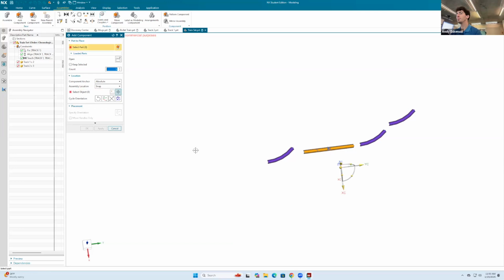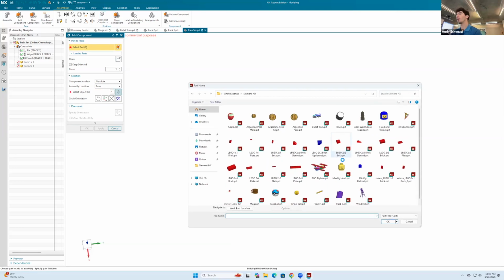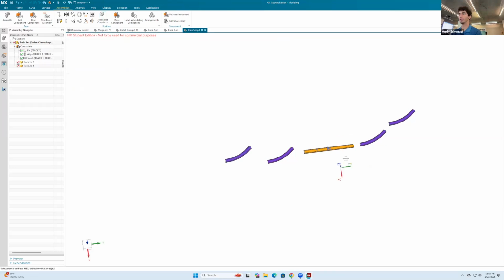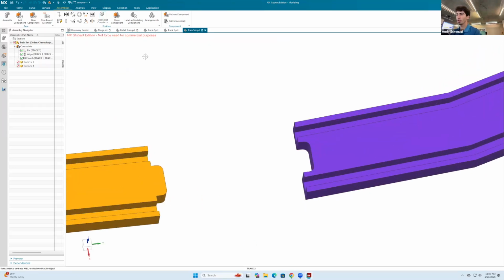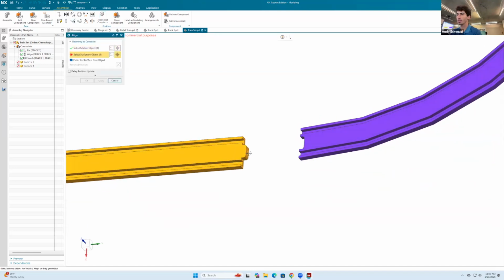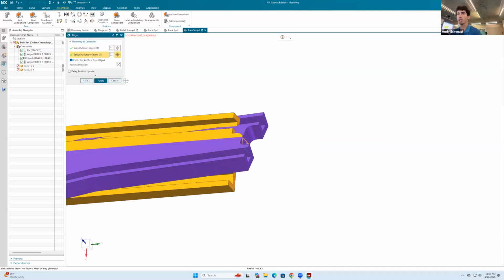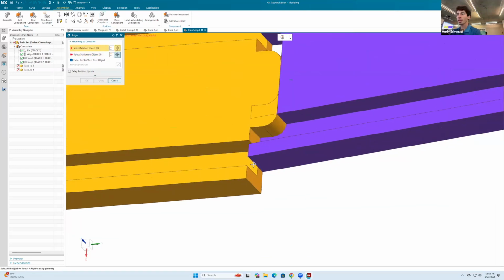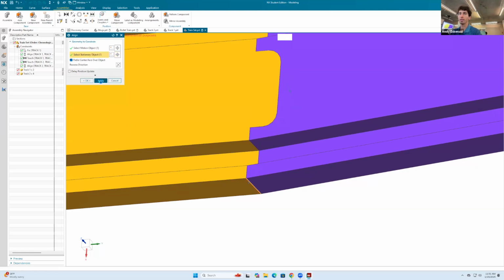So today is similar to what we did on Tuesday in a way, just adding the configurations element to this. So now what do we do? We go here to align, and I can say, all right, I want this face and that face to be aligned. Good, apply. And I want now that little line and that little line to be aligned. Excellent, there we go.